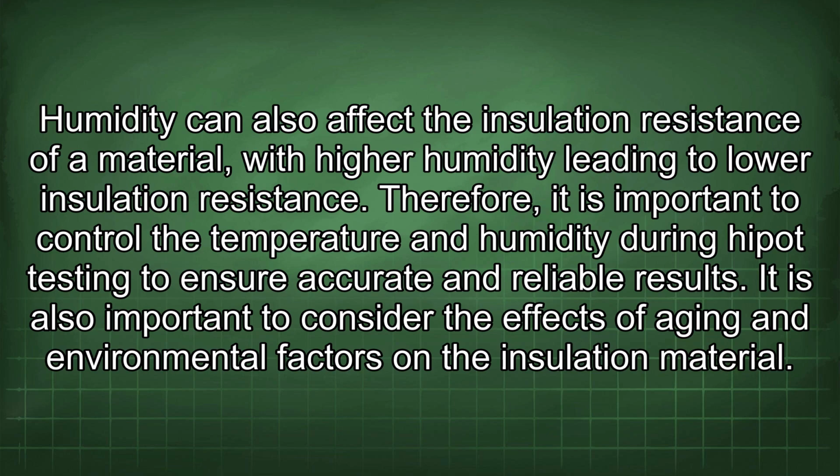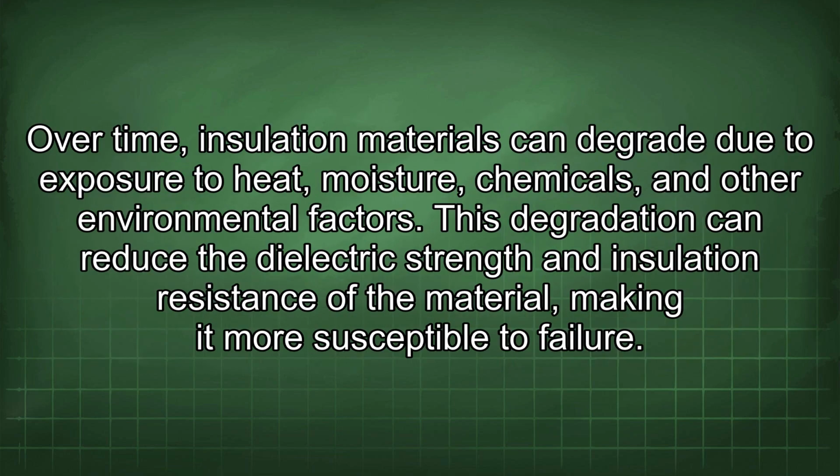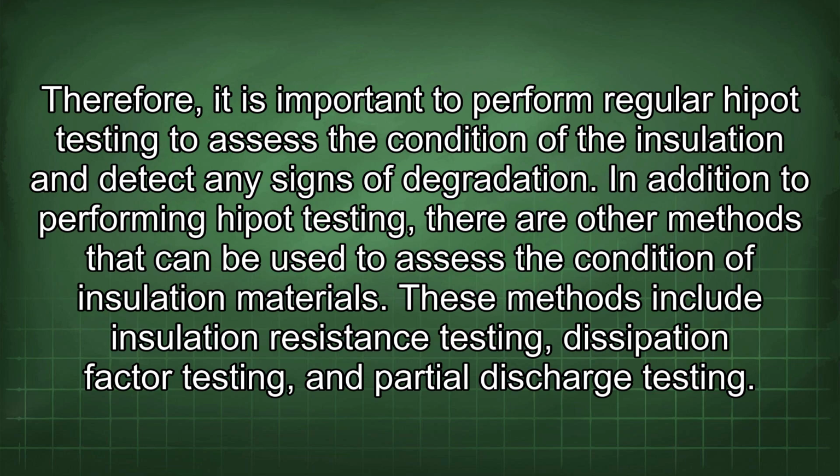It is also important to consider the effects of aging and environmental factors on the insulation material. Over time, insulation materials can degrade due to exposure to heat, moisture, chemicals, and other environmental factors. This degradation can reduce the dielectric strength and insulation resistance of the material, making it more susceptible to failure. Therefore, it is important to perform regular Hipot testing to assess the condition of the insulation and detect any signs